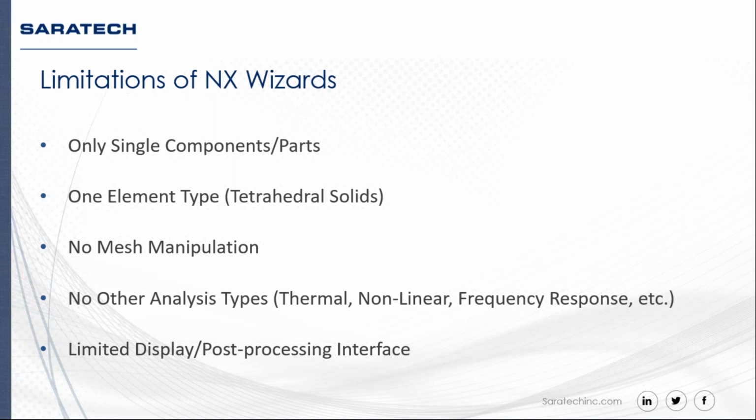Next, it only works with one element type, which is the tetrahedral solid. It's not too bad, as the tetrahedral solid is pretty versatile. It will take on any complex shape that you throw at it, and the results that it gives are pretty accurate.